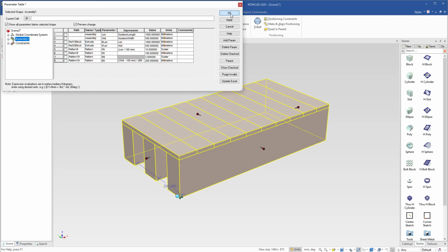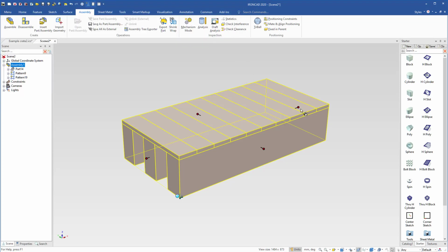And now if we go and hit OK to apply that, we can now go into our handles and right click on one of these, and we can say change snap increments. And one of the options here is to set what the linear snap increment is. In our case, it's going to be 100. And you can also choose to have this snap by default if you want on, or you can just hold your control key to do it. I just use the control key in my case and hit OK inside of there.